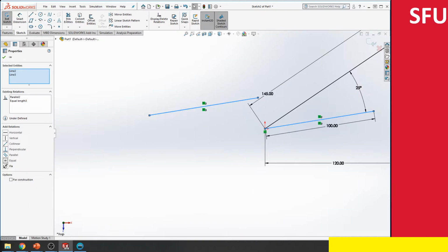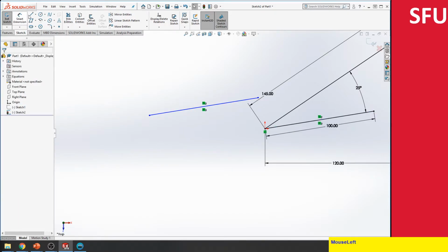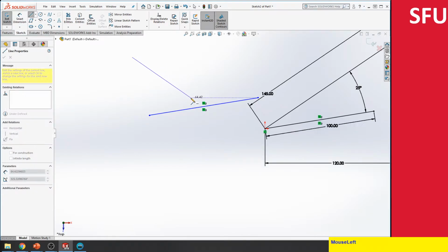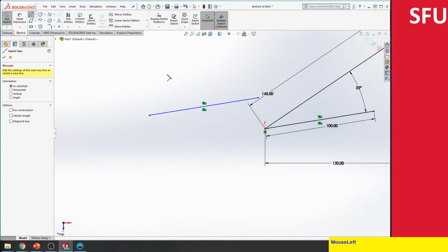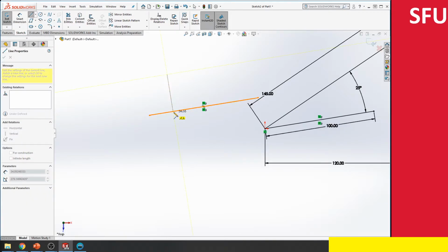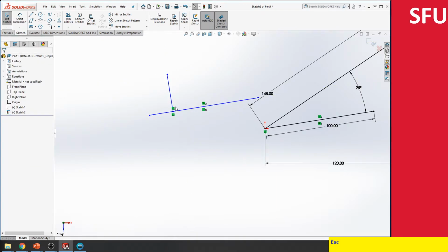We looked at the parallel from the geometry. And what you can also do is make lines perpendicular to each other. For that, let's do another line. There are a couple of ways you can impose the constraint. I can create the line and then add the constraint later on. But if I'm really careful, I can start and orient it very close to perpendicularity. Notice that a yellow line comes about, and it has automatically imposed a perpendicular constraint. It made this point coincident with the line,